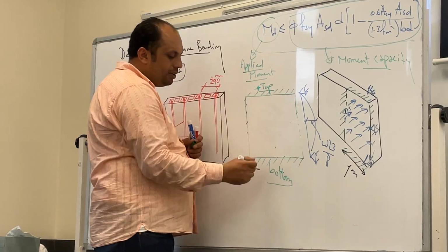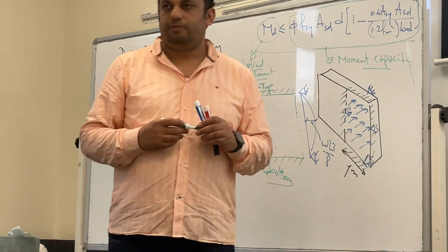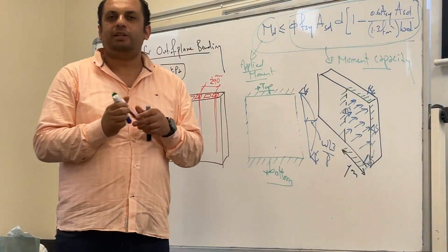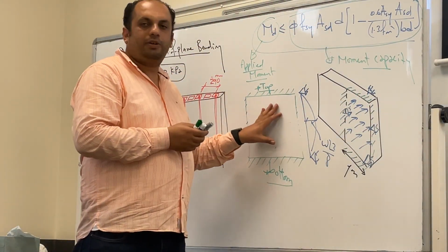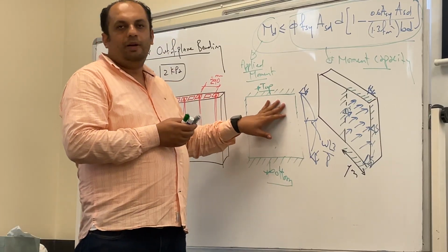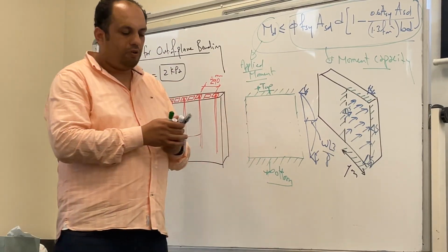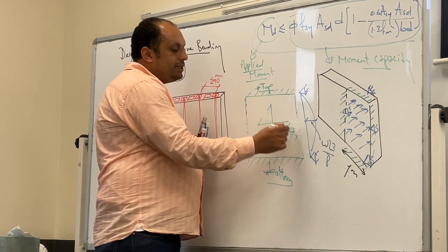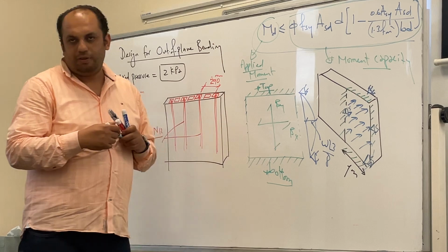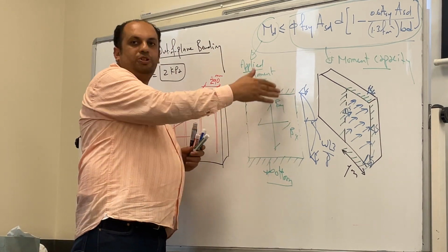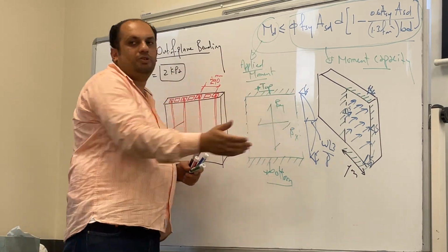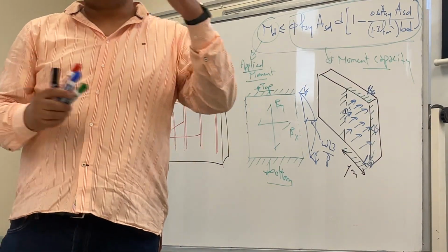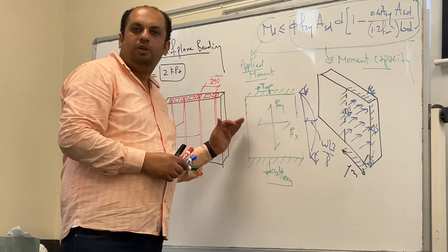If you've done something different, it's okay. Yeah, I did the two ways. If you want to do it two-way, the only thing I found online is that you can use the reinforced concrete slab approach. If it is supported by four supports, you can use the values of beta x and beta y to distribute the load. You can't say the whole load will go vertical and horizontal. The load is 100%, so a percentage will go vertical, and a percentage will go horizontal.